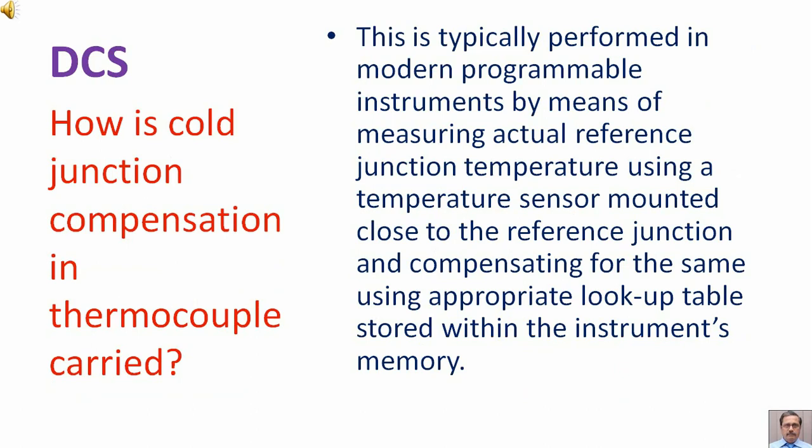How is cold junction compensation in a thermocouple carried out? This is typically performed in modern programmable instruments by measuring the actual reference junction temperature using a temperature sensor mounted close to the reference junction, and compensating for it using an appropriate lookup table stored within the instrument's memory.